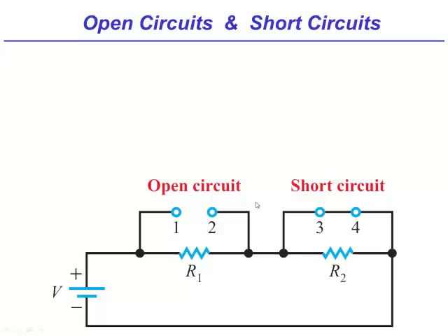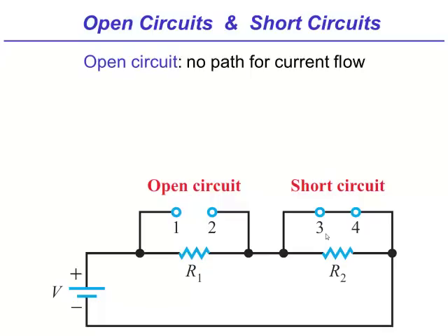All right, let's talk about open circuits and short circuits. These are terms you hear a lot. Oh, that's open, that's short. And so it's good to give you an intuitive grasp and also a definition of what exactly we mean. Okay? So an open circuit is just something where no current can flow down that path. So look at this, very simple. Just imagine there's literally a wire and it ends, and there's another wire that comes out of this point and it ends, and they're not connected by any metal or anything else in here, right? Pretend there was vacuum, if you will. And so no current can flow from 1 to 2. That's an open circuit. Okay, and I'll come back to that in a minute.